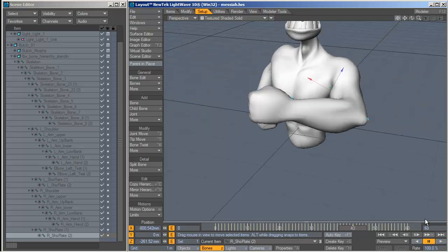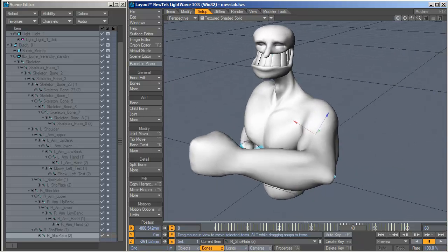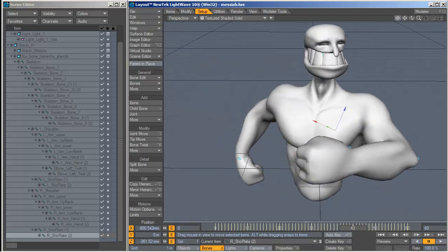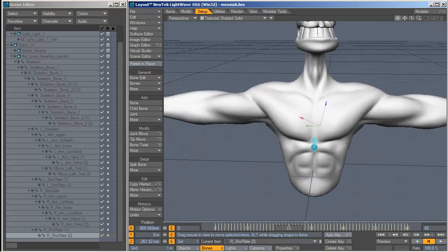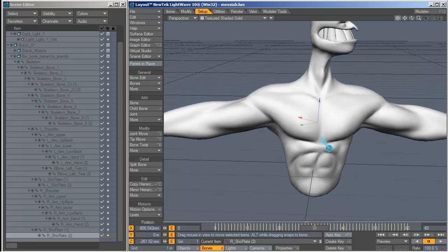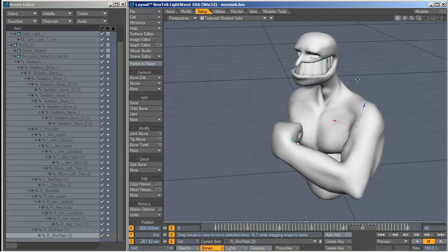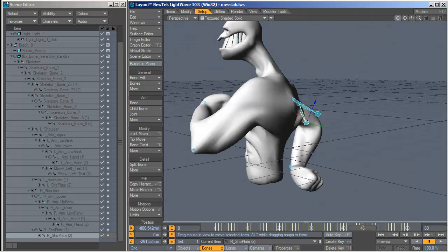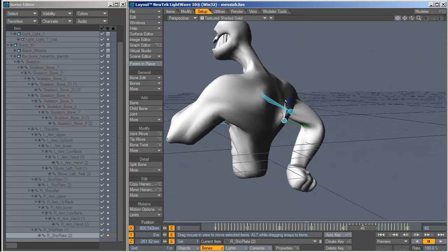What you're seeing is actually Lightwave's standard bone deformation. It's completely ignoring Messiah's generated weights, which is definitely not what we want. Although it's curious to notice that it does a really good job. As a matter of fact, Messiah's procedural weight generation system branched off from Lightwave many years ago, but it evolved from there, and that's what we want to use. Okay, so how do we do that?